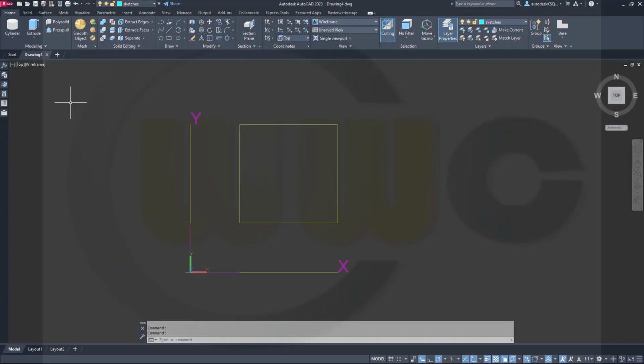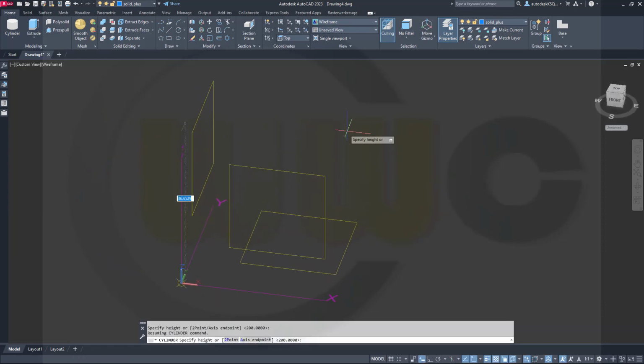So you could use solids for this exercise, or you could do it with sketches. Maybe I do sort of a mix. Let's start with a cylinder. And that cylinder should be, of course, on a different layer. So center should be at 0, 0. And the diameter should be 383. And the height should be 186.